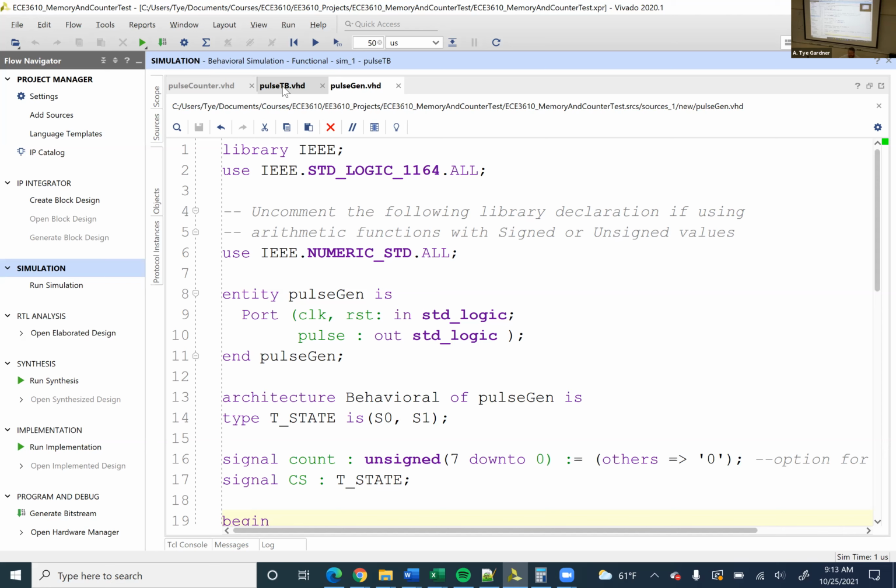Because if you have a sine wave programmed in memory and you want to vary that sine wave's rate, then all you have to do is change the rate at which you tell it to send out those samples. And so this doesn't allow us to just sit and have load. So let's build a counter that sends a pulse at a given rate.